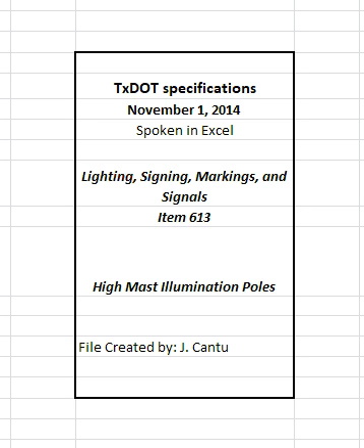3. Construction. Perform work in accordance with the details shown on the plans, and the requirements of this item. Provide components that fit together properly. Use established industry and utility safety practices when installing high mast poles located near overhead or underground utilities. Consult with the appropriate utility company before beginning work. 3.1 Standard design. Fabricate poles in accordance with this item and the plans. Alternate designs are not permitted.